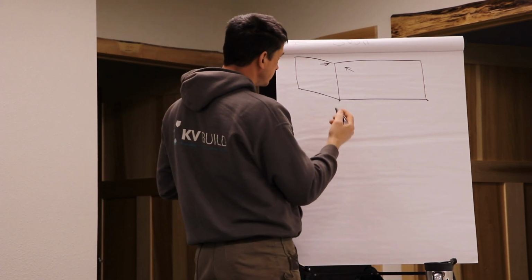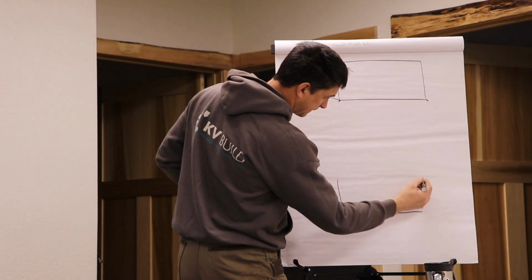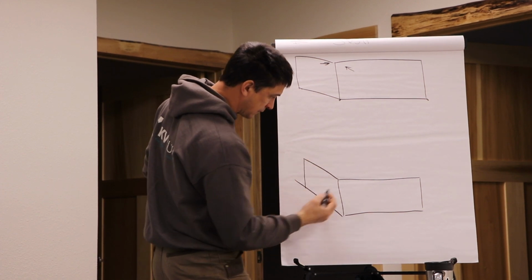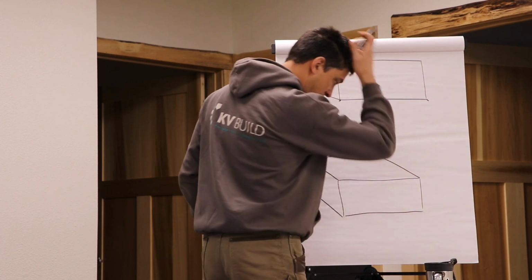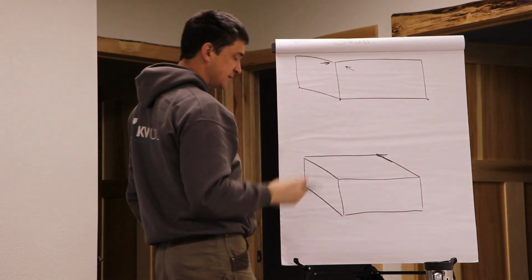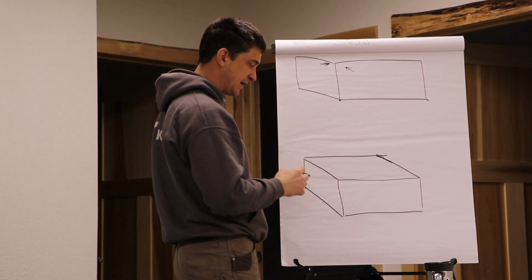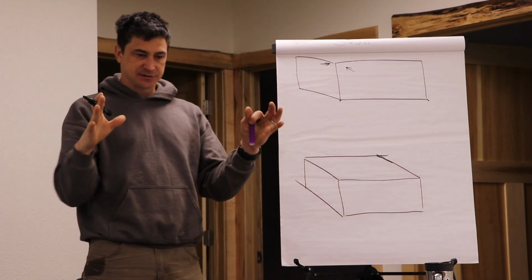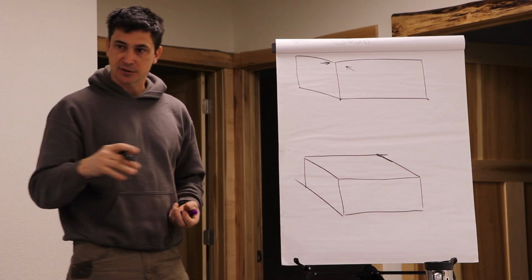Then, I guess I should have started this down lower. So here's my wall. And, well, that wasn't quite parallel, but we get all four of our walls braced, so that whatever direction the wind blows, this thing acts like a continuous box and it resists the loads in every direction.